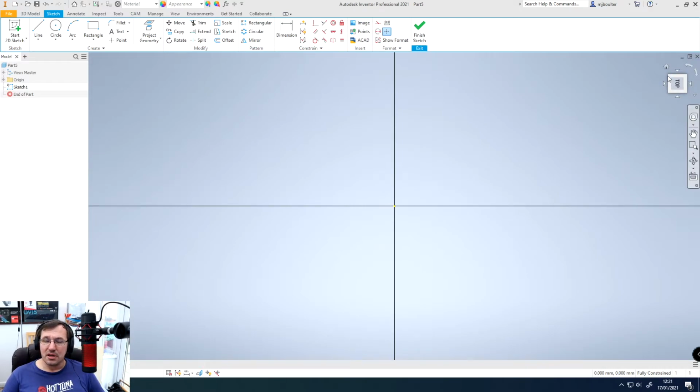as what's found in AutoCAD, and you'll have some series of pan, zoom, rotate, three-dimensional free orbit as it's called in Inventor on the right hand side, and this tab here you can move up and down depending on if you need to. When I'm starting a two-dimensional sketch, I always like to have it rotated so that it's orientated correctly. This is really important when we start using these dimensions and constraints functions, because sometimes you need to know which is the horizontal axis and which is the vertical axis.